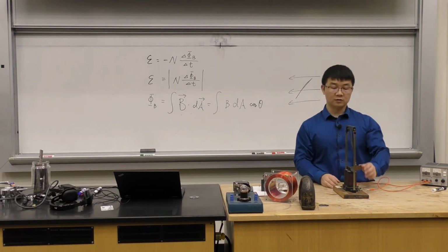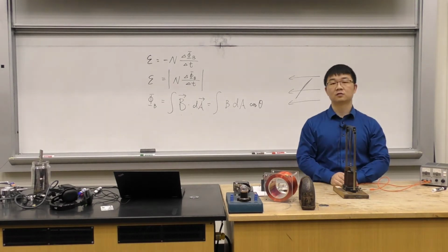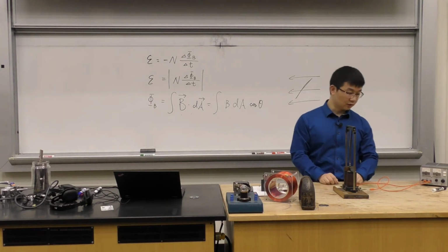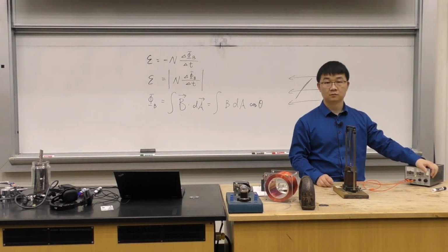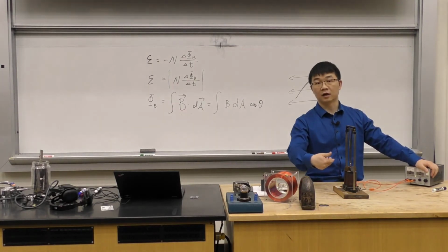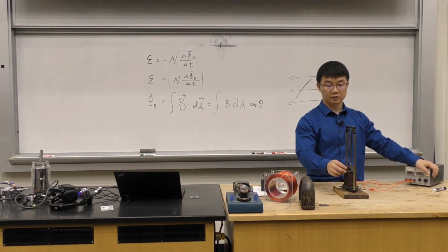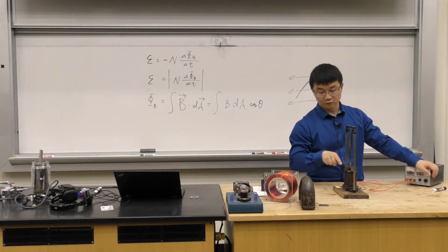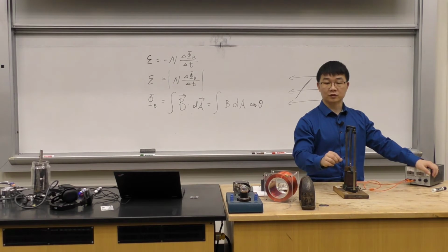They don't, right? It's because the eddy currents, the induced currents here, always fight the change. So they always want to slow down the motion. It's pretty much like a brake. I'm going to let it swing freely. Once I turn it on, it's going to stop. And they're not in contact. It's not this guy hitting these two solenoids, no. It's because now they become magnets. There's a magnetic field here, from either direction, doesn't matter. But I know that at the end, the induced currents are always going to slow down the motion in order to fight the change, right?